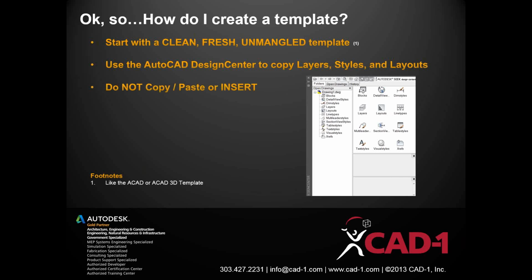Here's the biggest rule. Okay, I don't like using the Design Center. I'm just going to go into this old drawing, and I'm just going to do a copy-paste. Or I'm just going to use the insert command. No, do not do that. Because if you do a copy-paste from one drawing to another, it will bring over errors and reg apps and problems and things like that. If you insert one drawing into another, it will bring your reg apps and your errors. I have tested this. Trust me. Save yourself the time and effort. I've tested this on my computer. It will do it.